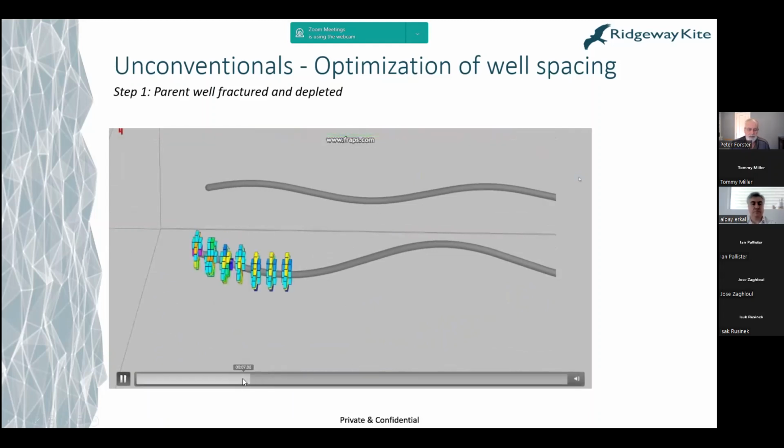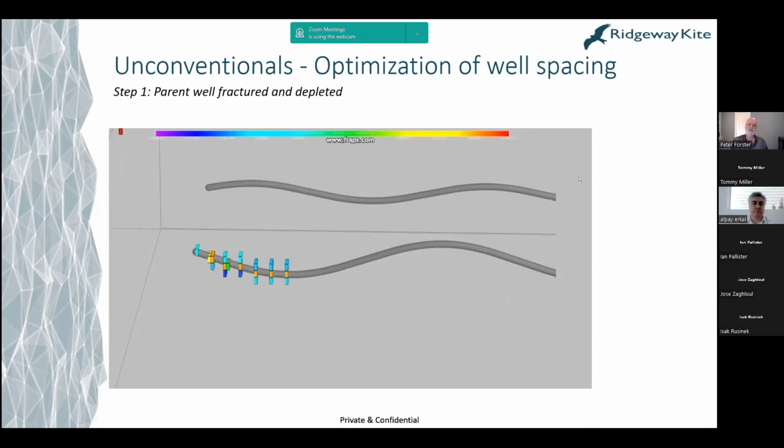If we look right here, we can see where the first clusters are initiating fracturing within the simulation grid. Here we've filtered what is visible to show just the cells where the breakage has occurred. So we've initiated fractures at these clusters, and as we keep pumping, these fractures will move out into the grid in 3 dimensions and will form an SRV.